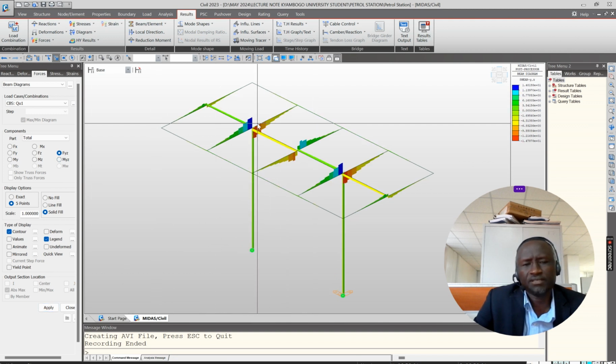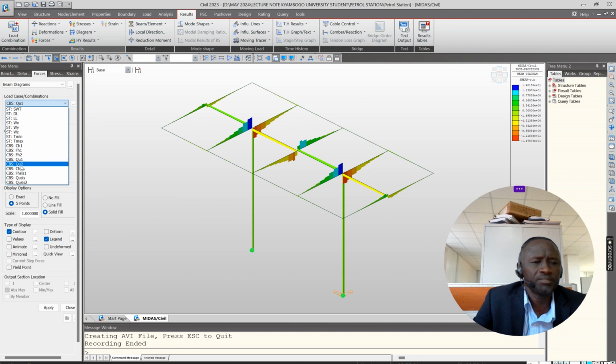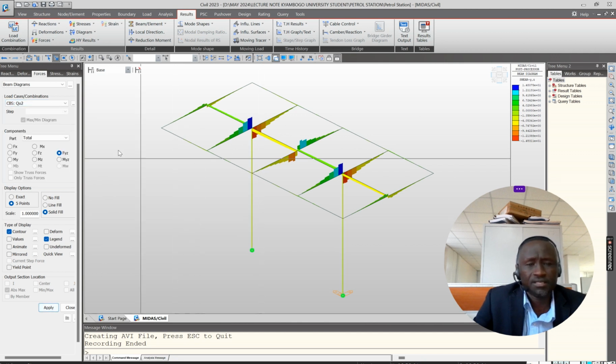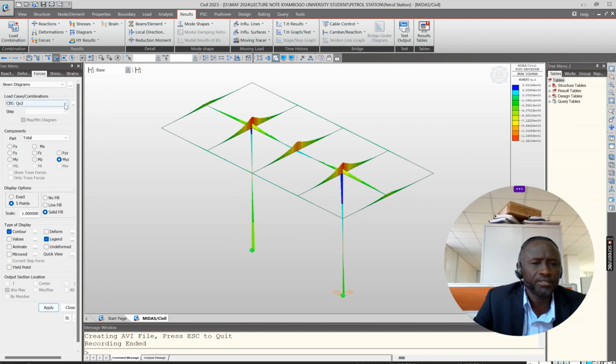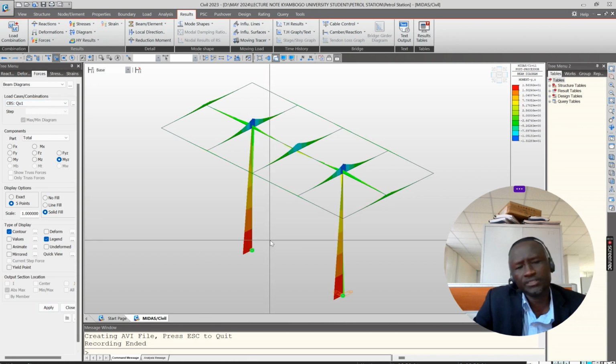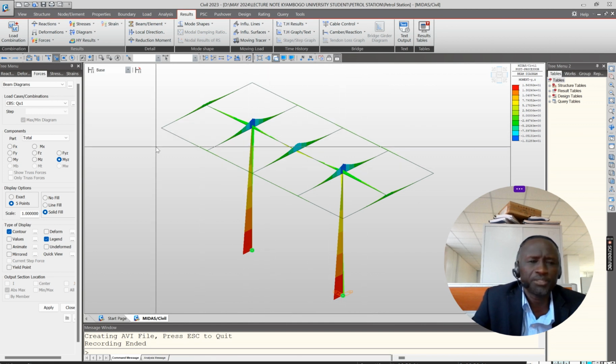You can see the canopy beams having very high moment forces and shear forces, so you have to be a bit careful with that. And so this is exactly the absolute load. Then this is the moment, where wind is in the shorter direction. This is how we look at it. So all these areas need special attention for most of this canopy.